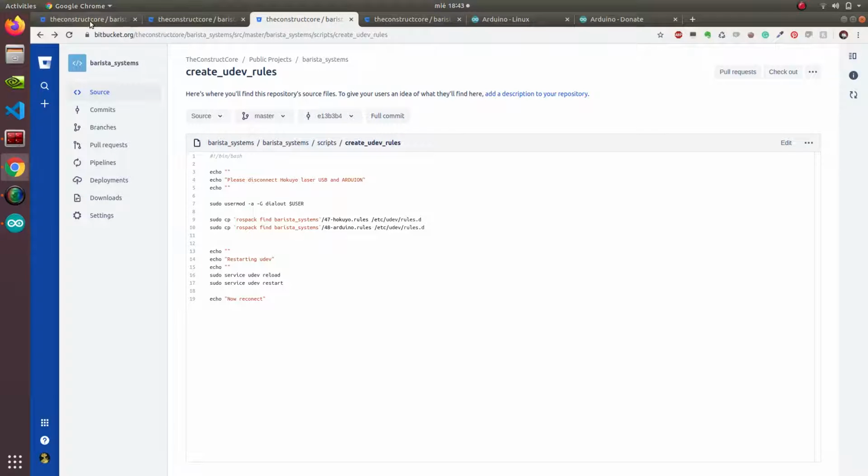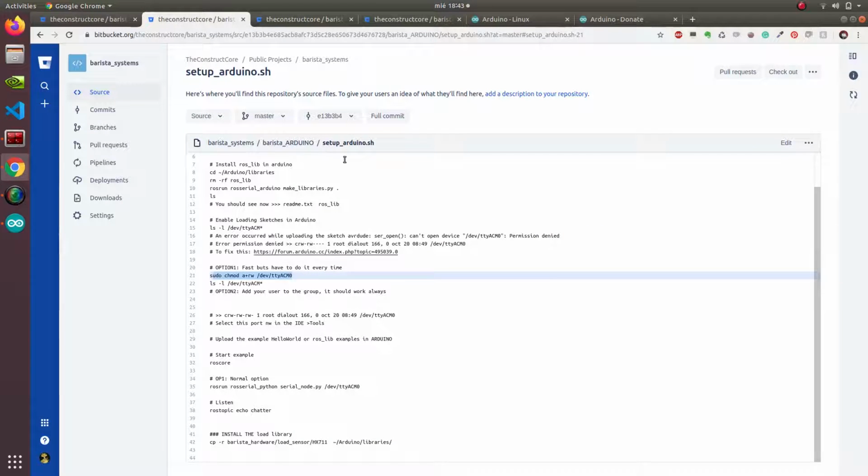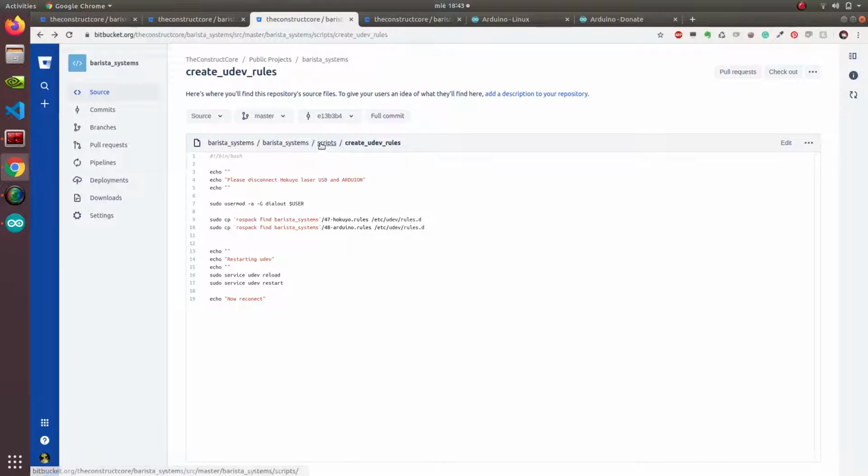In this case, you have to go to our Git, where you have all this information and other things that we are going to use during this video series. If you go to Barista scripts, create UDEV rules is a script that sets this in any device, when you have ROS installed.